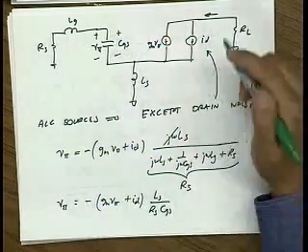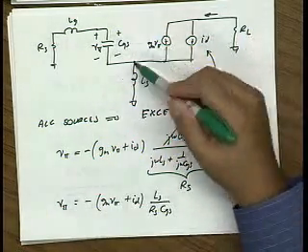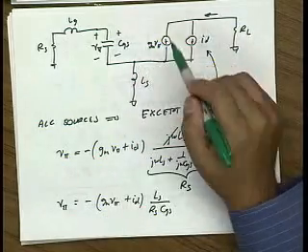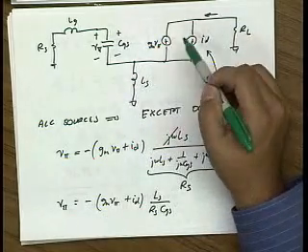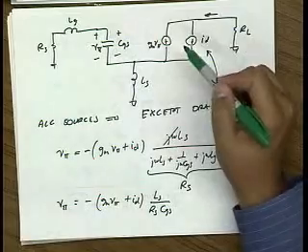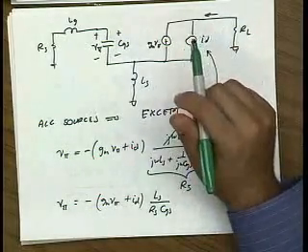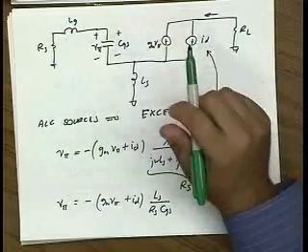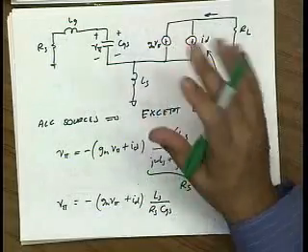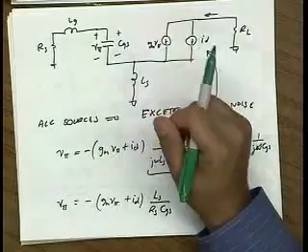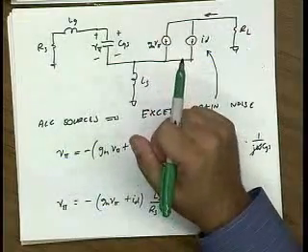Actually, you're right. In a real transistor, the GM has a phase shift, right? Nothing in nature happens instantly. So there will be a slight decorrelation, and so instead of being 1/4, it's going to be slightly different. But for all practical purposes, at say ft over 10, ft over 5, the phase shift is very small.